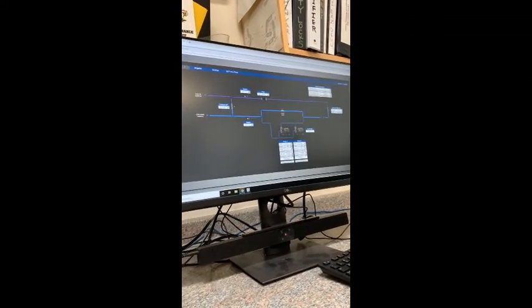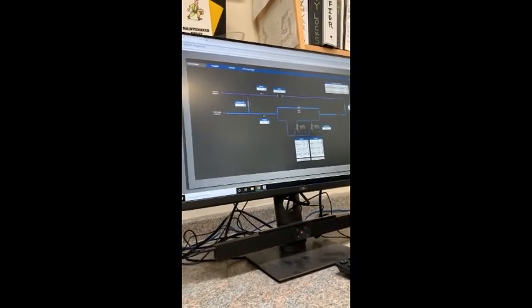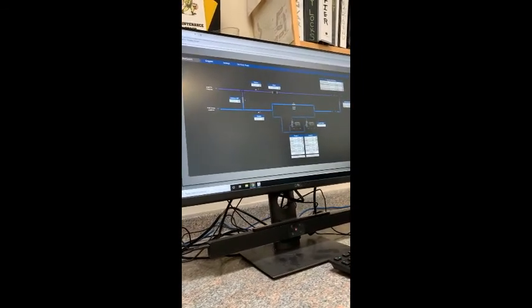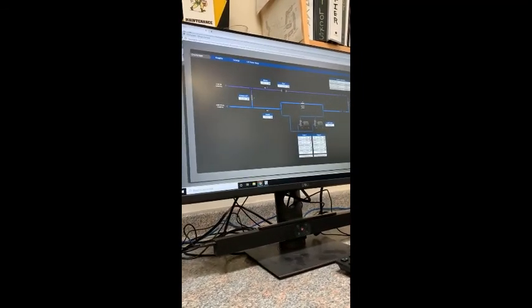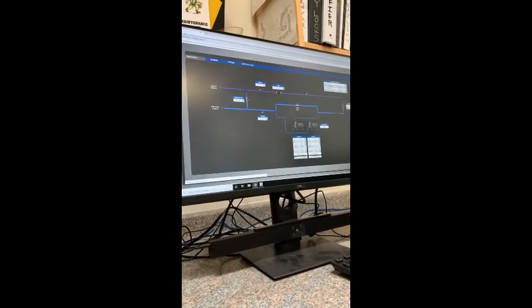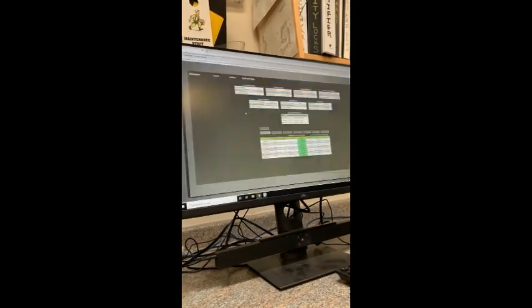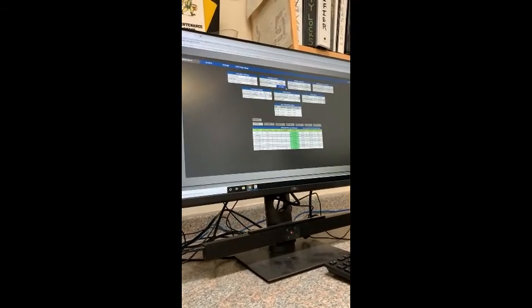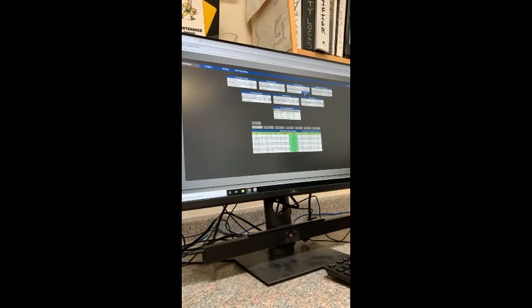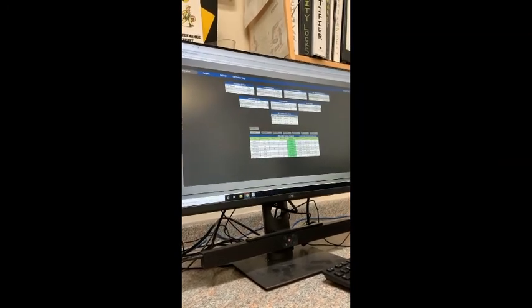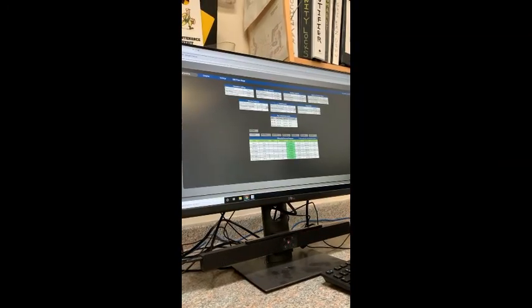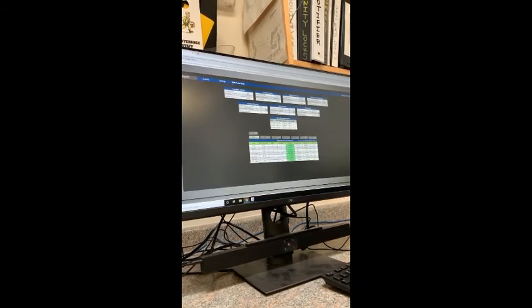So when the pumps are running, they'll control to this effective set point. Right now it's at 5, and that resets based off the differential pressure request resets. So that's changing constantly, I guess. Yeah, it will change as long as there's demand for it to change. And again, that's all part of the sequence here. It's a whole bunch of different settings and time frames and looking at the valves.